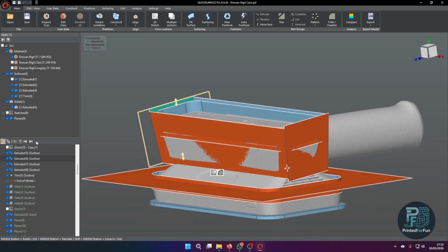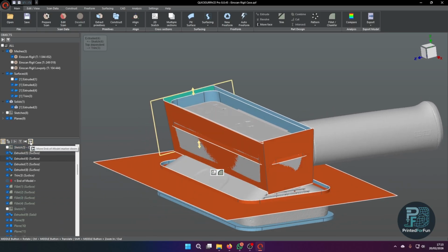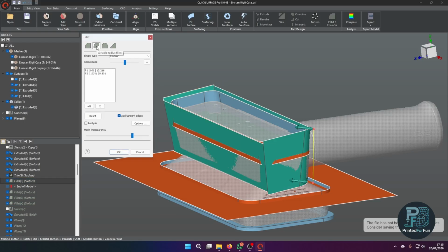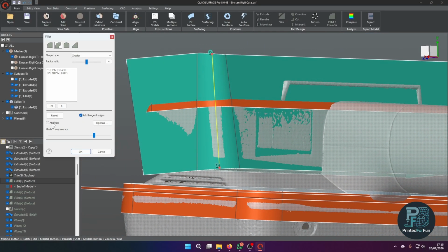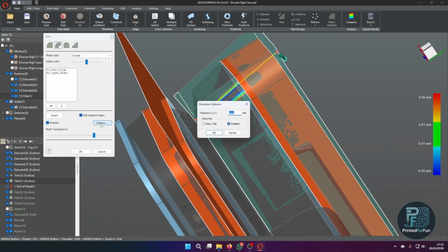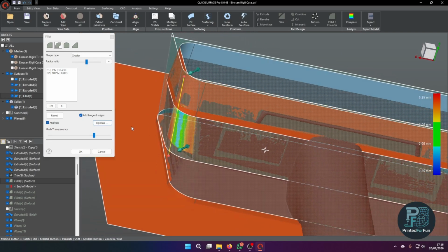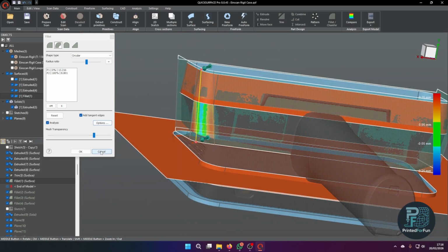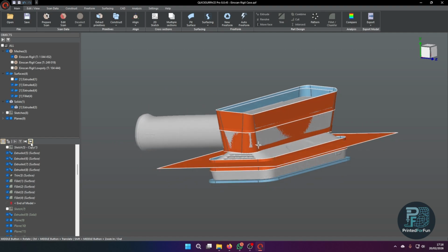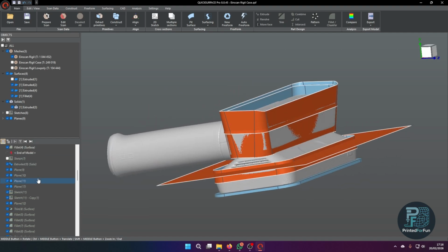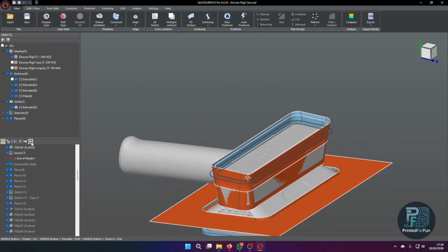On this sleeve I can now apply dynamic, or variable radius fillets to try to hit my approach here. If I look at the analysis function, maybe let's go back to 0.05 millimeters again. This looks quite right. Again, we are TPU printing, and I will do this approach on all 4 edges. You will also recognize this design approach later in further steps.